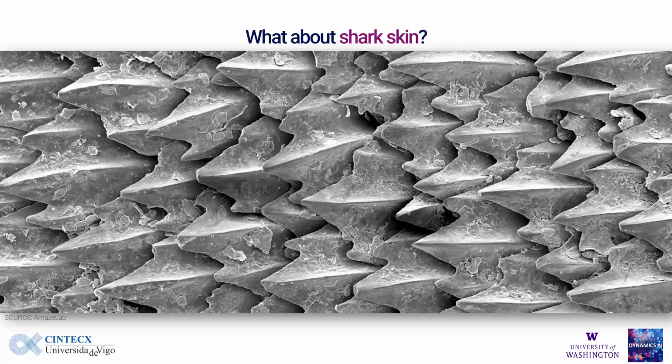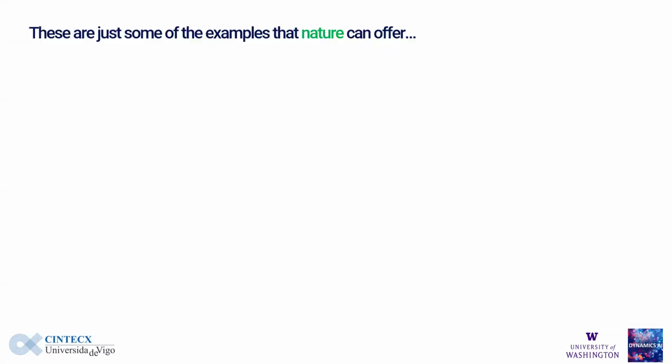This has a lot to do with heat efficiency regarding fins, because when you are trying to optimize heat transfer for microfins or fins in general, you both have to increase the heat transfer from the surface, but also try to decrease pressure drop as well. So these are going to be the two main targets that we are going to be focusing on today when we are trying to design new shapes for fins.